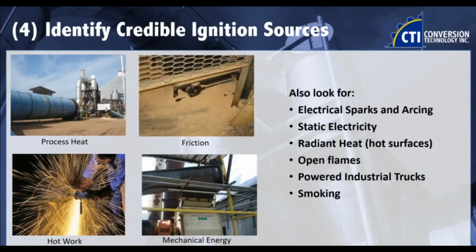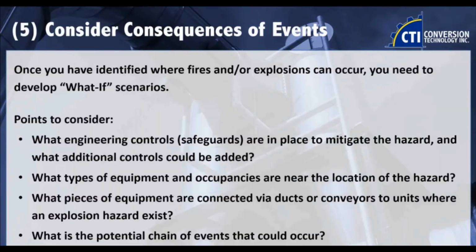But so identifying those, the open flames, dust blanketed motors, things like that, that's really going to show you where the hazards can occur. And then once you know what equipment you have and how an incident can occur, you want to look at it from a what if. Well, what if something goes wrong? What if there's a deflagration?